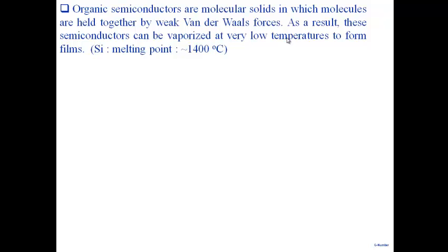What I can do is I can take a crucible, put some AlQ3 material in it, right? And I have a substrate on top. You guys will be doing the lab also. Then you heat the crucible to 150 degrees Celsius, right? And as you heat it up, it vaporizes. And if the chamber is evacuated, then these molecules which come out, they come out with a little bit of energy. So they'll just straight away travel to the substrate. Substrate is cold, and they go and stick to it, right?